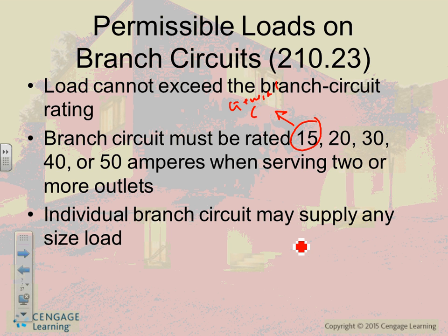branch circuit in a dwelling, guys. Ignore this one in a commercial. In a dwelling, this is your general branch circuit. Anything that the code doesn't tell you to use 20, what do you use? 15. Almost everywhere else, that's your general light and receptacle. By the way, it's L for light plus R for receptacle, both.